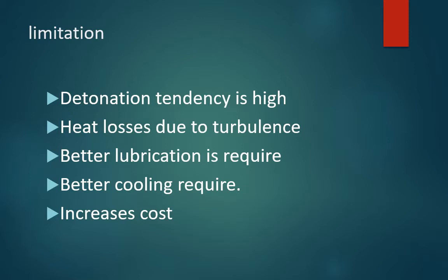So if we increase the operating pressure, we need to ensure that the engine structure, the cylinder block, and other components have been strengthened, right? Such that they can withstand these higher mechanical loads. Am I right? So that comes to the point that, due to increased pressure, the engine components should be capable of withstanding the higher pressure exerted by the cylinder components, right? So obviously that could increase the cost of the engine because of supercharging.